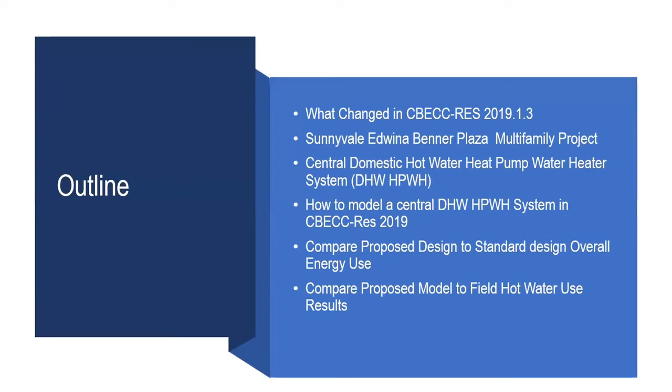First I'll be talking about what changed in the CBECC-Res 2019.1.3 version. And then I'll introduce a little bit about the project that we used for this analysis, the Sunnyvale Edwina Benner Plaza multifamily project. This project includes a central domestic hot water heat pump water heater system, and I will be showing you very briefly how to model it in CBECC-Res 2019.